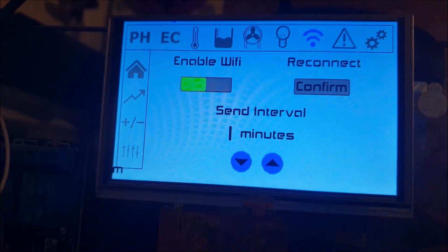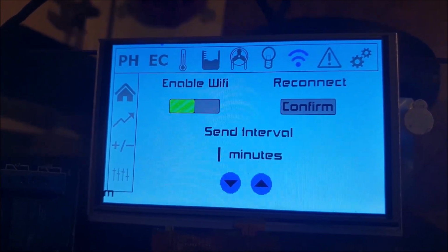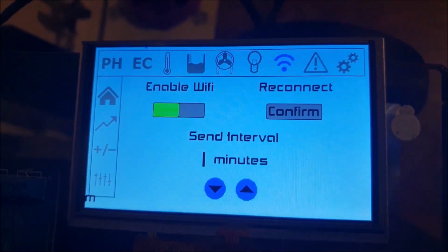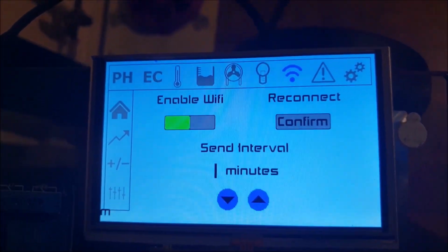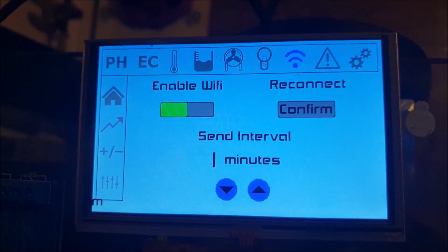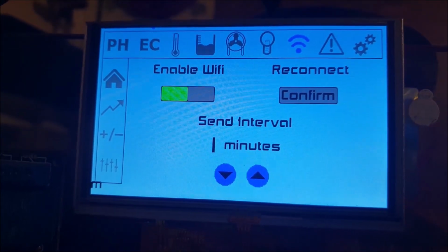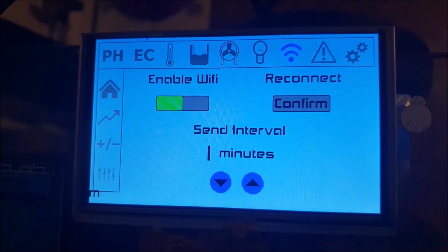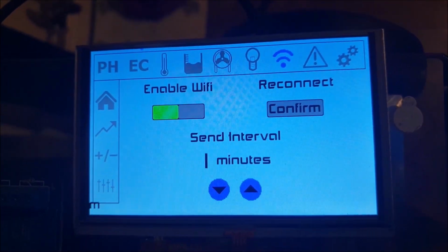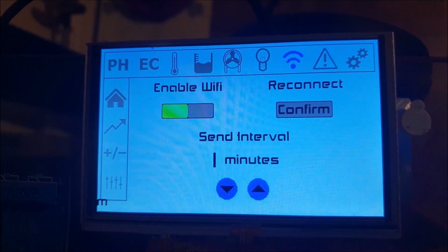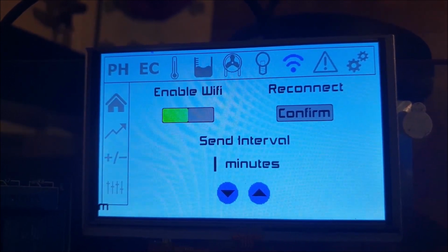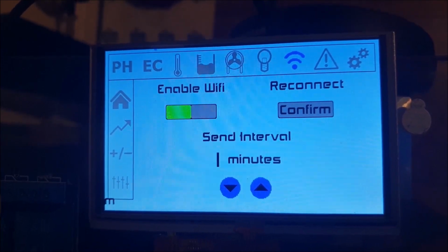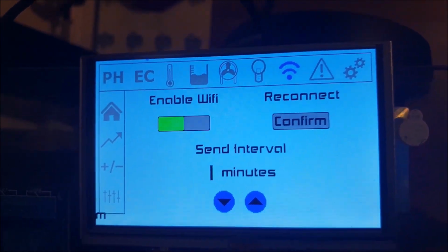Like I said, they're saved in EEPROM, as long as you click save each time before you turn off the device. After it's been running realistically for a whole month, it would have a value in probably every one of those array blocks, or at least the ones that are always being used, and it would get a very accurate picture of exactly how much to dose the pH up or down or EC to get to the exact target point required based on the current reading.